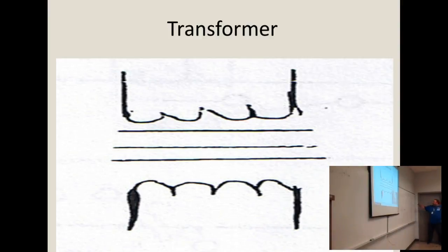And so I will step it down by 10 to 1. So putting 240 in, I get 24 volts, and that'd be my control voltage out. Okay? What if I stepped it up from 1,000 to 10,000? Then I would be stepping it up 10 times, right? That would give me 2,400. That's how transformers are made.